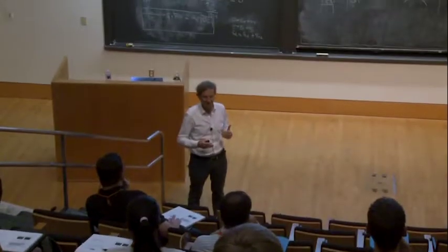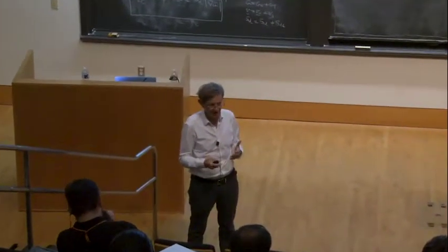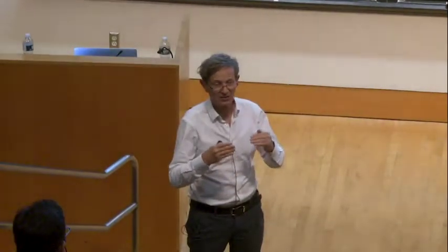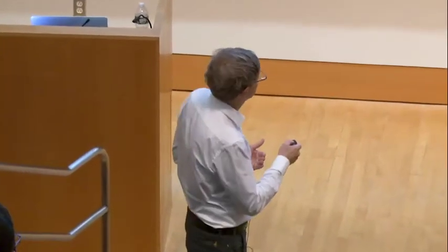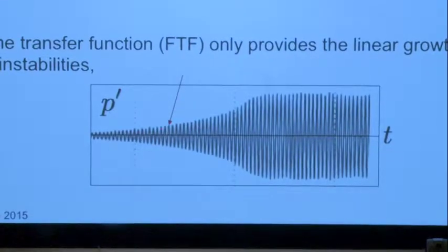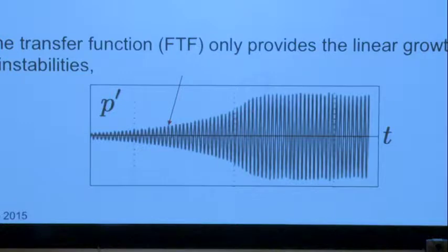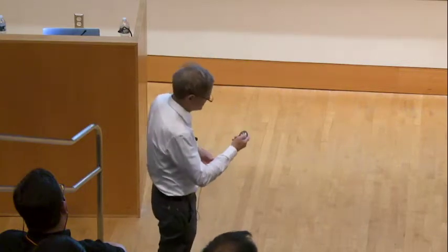The idea is the following. If the input level becomes large, you have nonlinear effects. So perhaps the transfer function may be a function of the level. So what you get is a family of transfer functions. And if you look at oscillations, the transfer function is good for this linear regime here. When you get to the limit cycle, you need something which is dependent on the amplitude, and this is the describing function. It's a set of transfer functions. We will see that later.